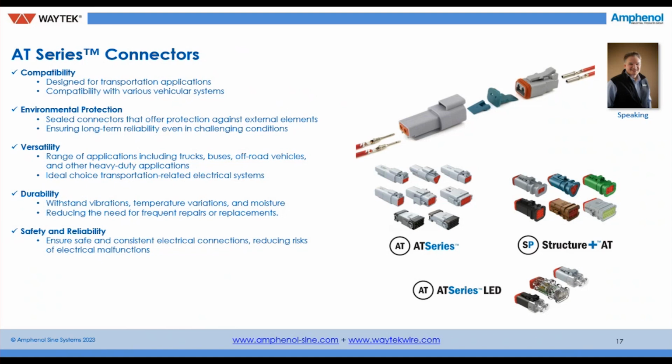And when you look at that Structure Plus connector, and you look at the connector that's up at the top, you say, wait a minute, there's a little bit of added structure there. Well, what we've done there is we've added that additional structure in case a customer wants to put heat shrink or glue shrink to dress up a connection system. Maybe they have extreme washdown environments like some lawn mowing equipment or ag equipment. Added protection in the form of glue shrink or heat shrink could certainly add to that.